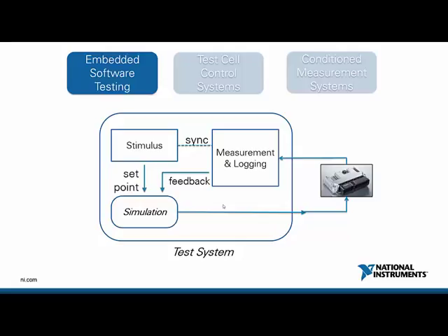We're logging the data in the closed loop system, and we're providing stimulus, so we're essentially driving the ECU. And we're also doing mathematical simulation or electrical simulation. So we're connecting our ECU to maybe a PXI system that's running a simulation model that represents maybe the engine or the whole vehicle to virtually drive the car. And then we're providing stimulus to actually run the tests and doing logging.